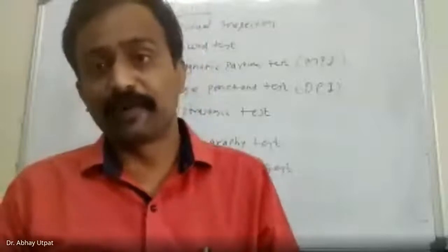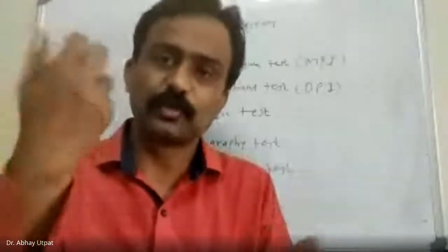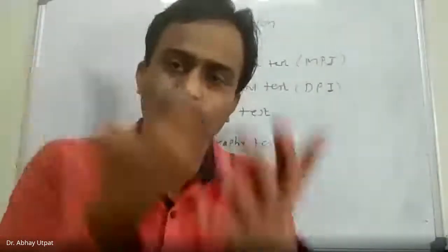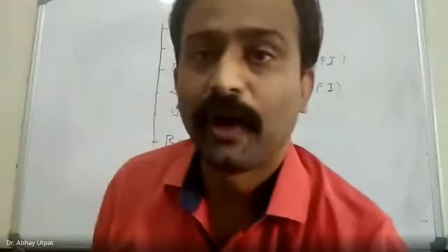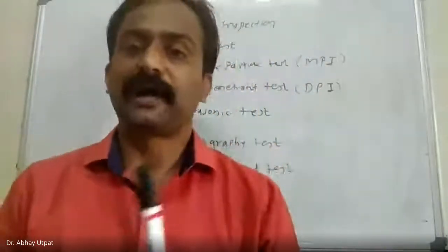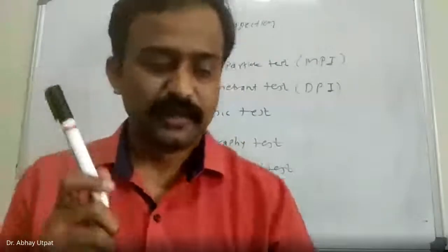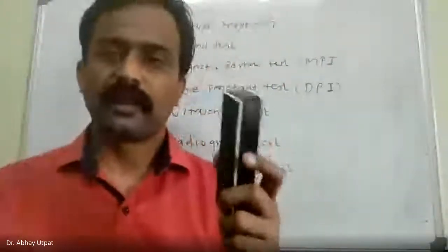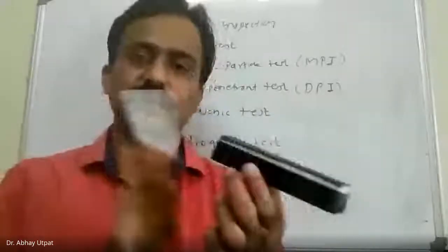But now we are playing with metals, not with other pots. You can't take a stone and make impact, or do it by your fingers. So you have to check it with an iron rod or steel rod. You have to take this steel rod and apply it on your casting in this way.